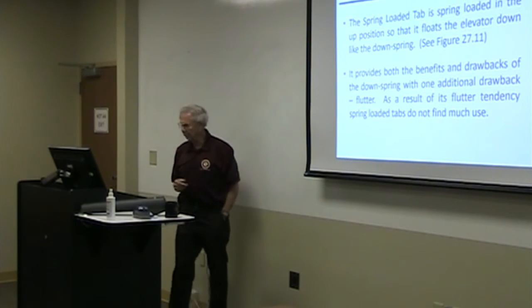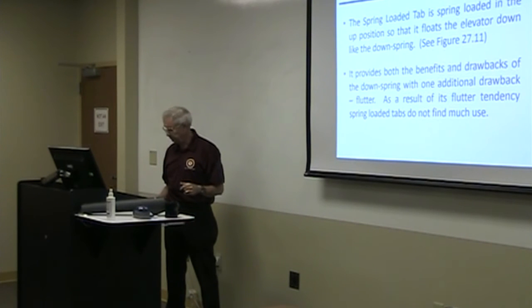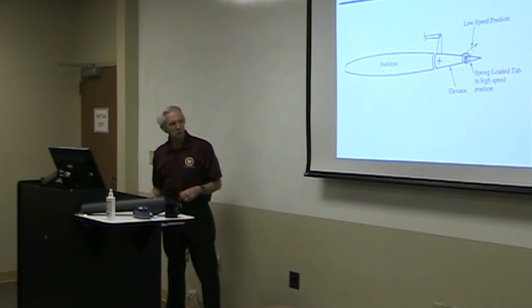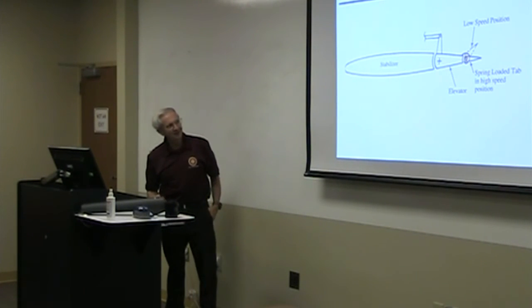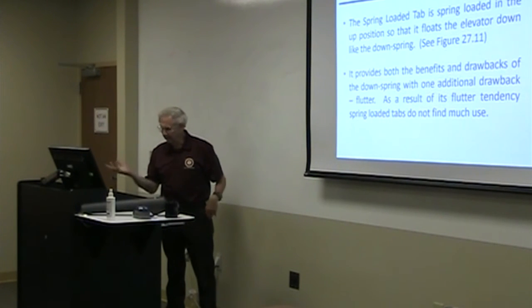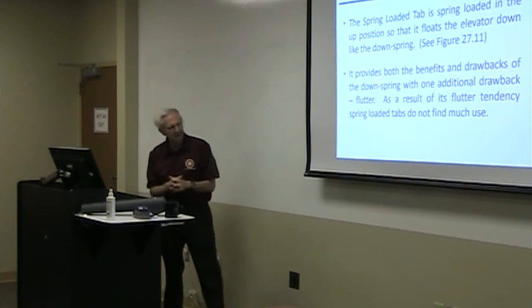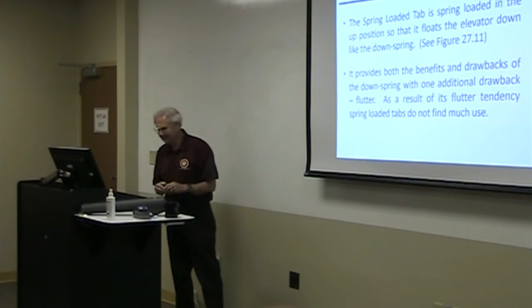Okay, spring-loaded tab. Well, spring-loaded tab is loaded in the up position so that it floats the elevator down like the down spring. Here's a picture of one. It provides the benefits and drawbacks of a down spring with one additional, and that's flutter. And as a result of the flutter tendency, you don't see them very much in use, but it's a possibility.